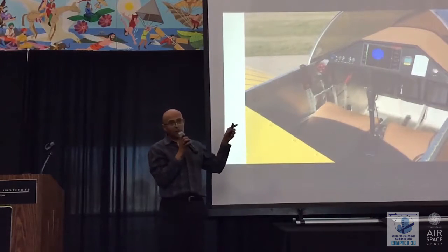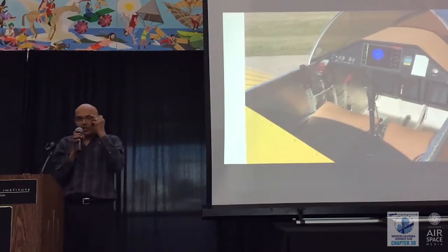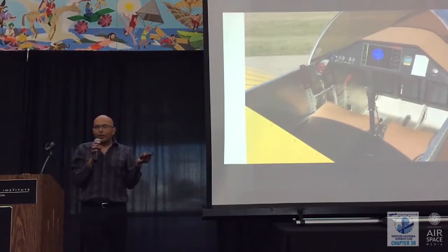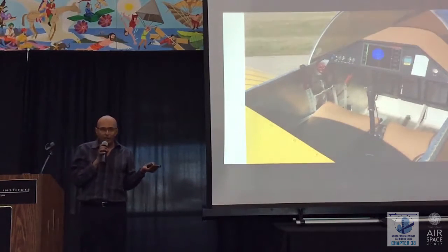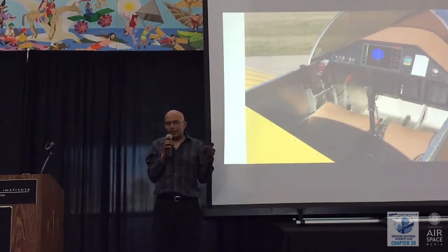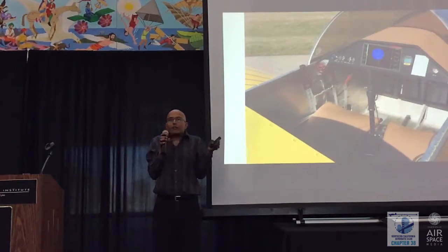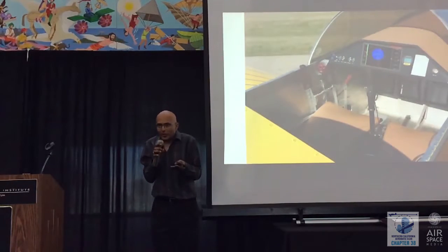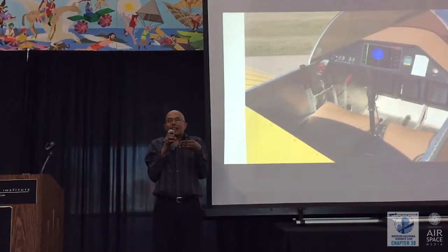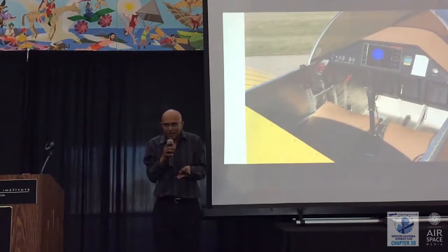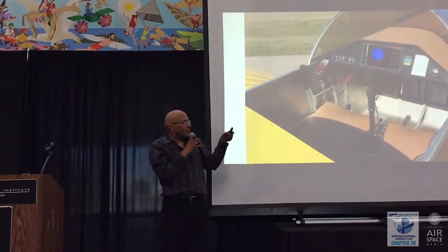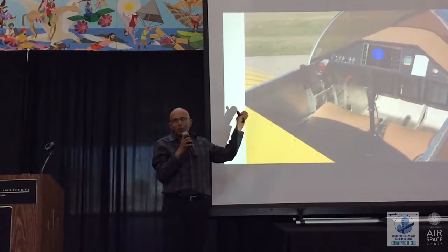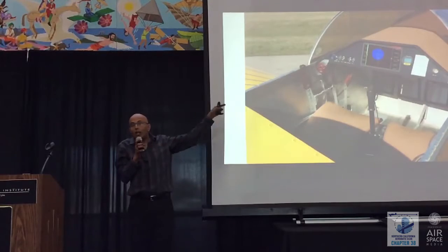And finally, back to the PFD. A lot of people are building small, inexpensive aircraft, usually experimental aircraft. The first thing they put in there is an artificial horizon, even though they're never going to fly in actual instrument conditions, they're not going to ever fly into clouds. And if I had a certain number of dollars to spend on instruments, I would much rather see the thing that I can't actually see by looking out the window. And that is the actual air data. So if I had my druthers, a simple experimental aircraft with just one instrument would look like this.